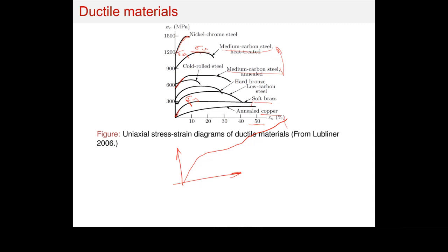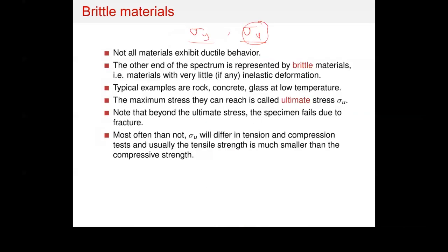So slightly higher, well within the plastic range, and immediately after that, the material would start to fail. So the necking behavior would start to become quite clear, and it's just going to lead into failure. So these are the two numbers I want you to remember. And when I'm going to discuss failure, I'm going to discuss failure relative to these two numbers.